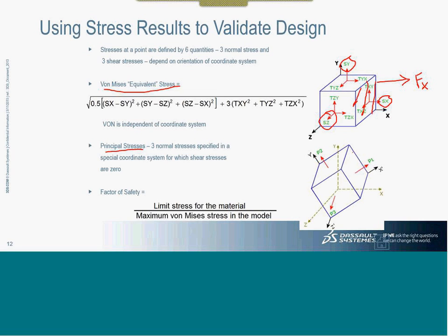Now in the actual geometry, even if the force is applied somewhere in the geometry, when it is localized into that element, it is typically further divided into X, Y, Z directions applied on that particular element. When post-processing after analysis is done and the strains are seen, we basically get the strains in the X, Y, Z direction. Those are converted into the X, Y, Z stresses in the planar direction, that is SX, SY, and SZ.